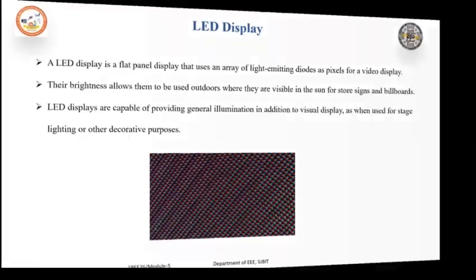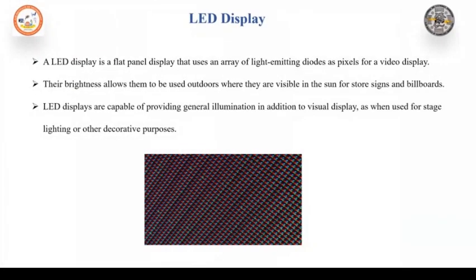What are the advantages of LEDs? The advantage is smooth control of light intensity from an LED, because light output from an LED is a function of the current flowing through it. LEDs are economical and have a high degree of reliability because they are manufactured with the same type of technology used for transistors and ICs. LEDs are rugged and can therefore withstand shocks and vibrations. LEDs can be operated over a wide temperature range. The switching time is always less than 1 nanosecond, so they are very suitable where dynamic operation of a large number of arrays is involved.